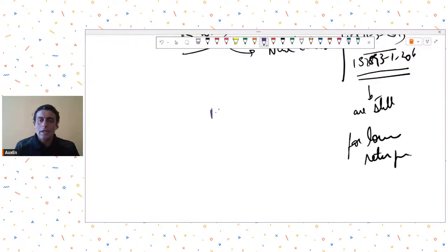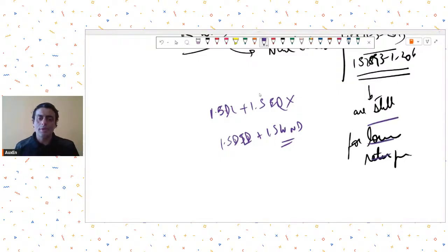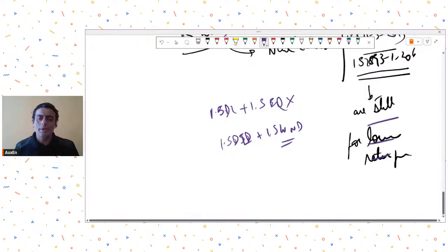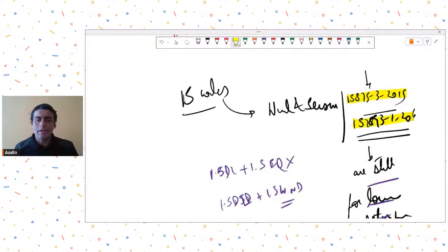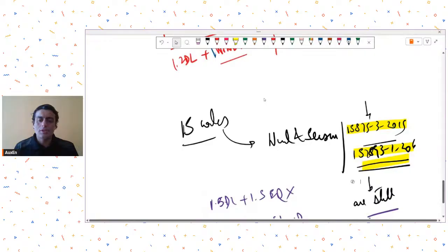And that is why in Indian code we still have combinations like this. So we will have 1.5 plus 1.5 like this, or we may have 1.5 dead plus 1.5 wind like this. Why? Because our return periods were for a lower return period. So the problem is the jugglery these MBMA people are doing: they take the loads from these codes, which are for a lower return period, and then they use the load combinations like this. So that is a big mistake.